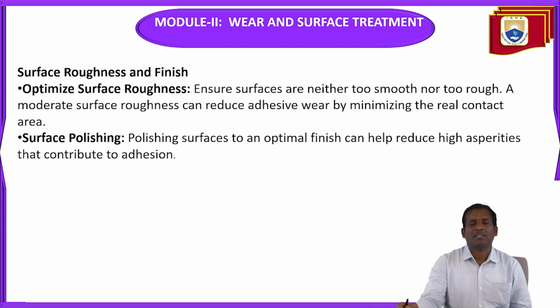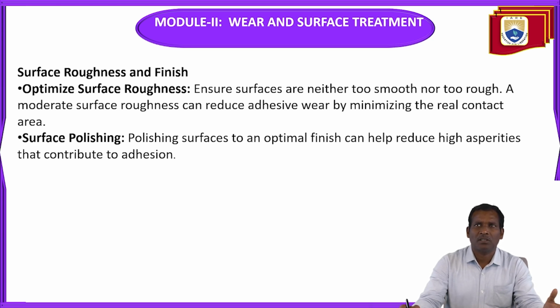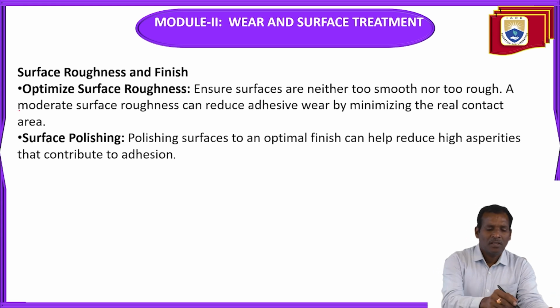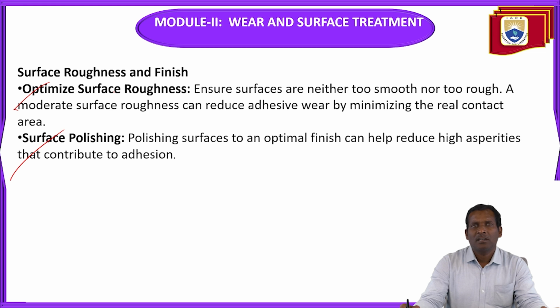Next, surface roughness and finish. Optimize surface roughness. Ensure surfaces are neither too smooth nor too rough. A moderate surface roughness can reduce adhesive wear by minimizing the real contact area. And polishing surfaces to an optimal finish can help reduce high asperities that contribute to adhesion.